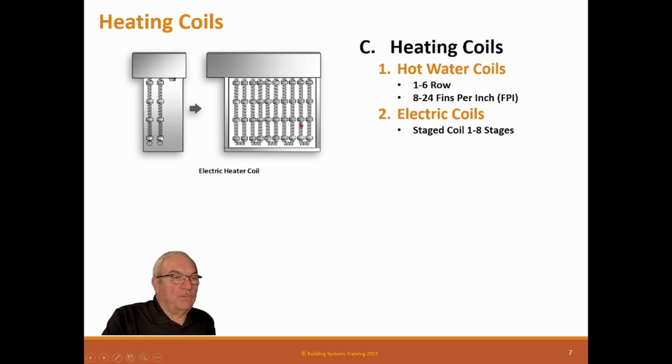The only thing that's important about electric coils is air velocity. You can't have dead spots in this coil because this is a standard coil, and you notice that these heating elements are exposed. So if you have an area that has no flow, those coils will heat up, get too hot, and burn out. So you have to have velocity across this coil. And then right here is a thermal element that watches that. If it gets too hot, it shuts off the heater.